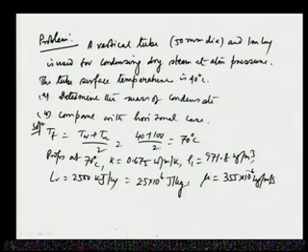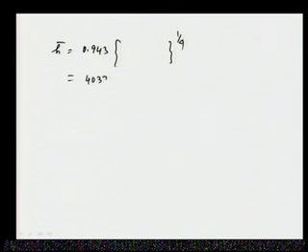Fine. Now, we assume rho L minus rho V is nearly equal to rho L, because the density of the vapor is much lower than the density of the liquid. So, when putting in the expression H bar equal to 0.943 into the whole expression to the power 1 by 4, whatever we have discussed, this value is coming to be 4033 watt per meter square per Kelvin.